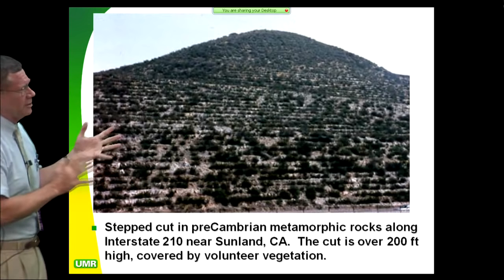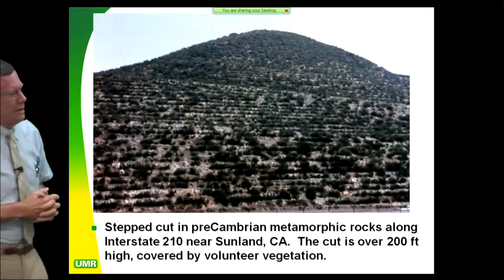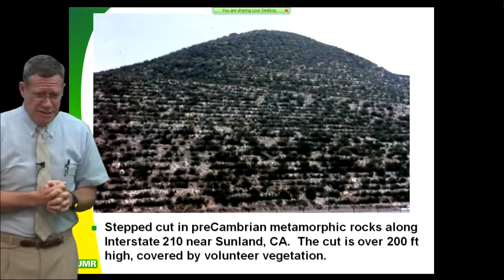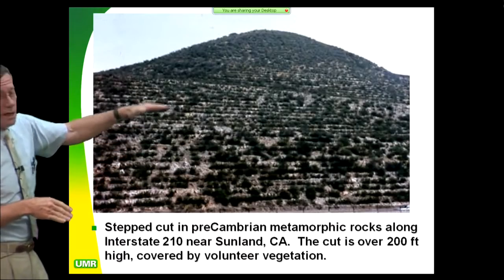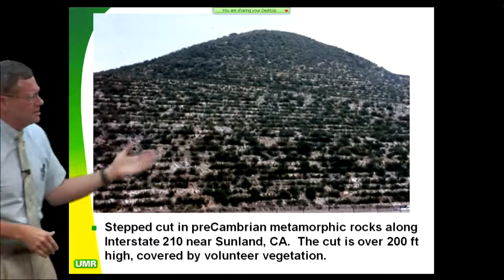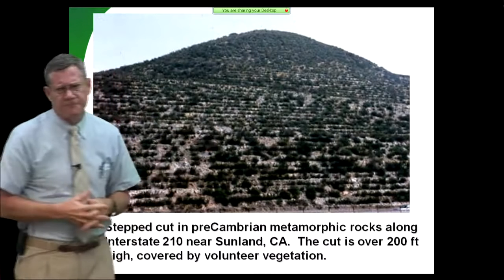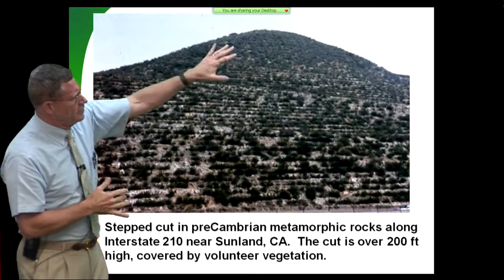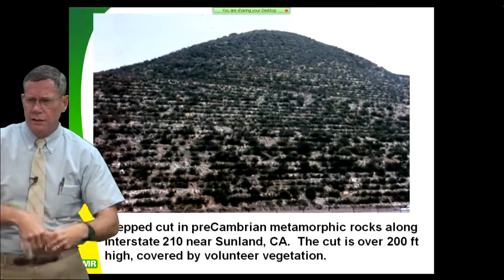But you're in Southern California, near LA, where everything has been tectonized and sheared and lifted up out of the basement very, very rapidly. We're not far here from the San Gabriel-Cucamonga fault system, so this has been lifted up very rapidly, probably something around 6 to 13 millimeters a year, in that range. And so the state came in here and made stepped cuts, like they make in Arizona. Stepped cuts are where you go up 3 over 6, up 3 over 6, doing a 2-to-1 slope. This is a 1.5-to-1 slope, so they're going up 4.5 over 6, getting a 1.5-to-1 slope, which is about 33 degrees. They're stepping it because they're trying to break up the formation of erosional rivulets or gullies that would get down here and then accumulate little talus cones out onto the shoulder of the highway.